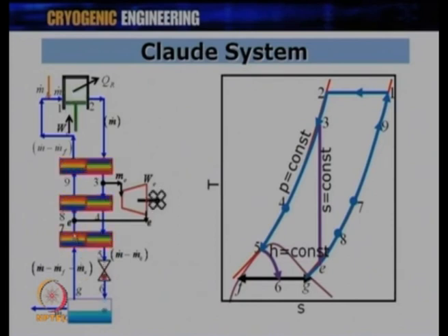At this point, the gas comes out at 7. So, you can see from here it comes to 7, which is on the higher temperature side, because it matches with the temperature 4. However, the cold gas which is expanded from 3 to E comes at a much lower temperature, as you can see. It will depend on where the point number 3 is. Okay, in a TS diagram, depending on where point 3 is, the point E would be decided, and this stream which is coming at point 7 will combine with the Me flow rate coming out at temperature at point E.